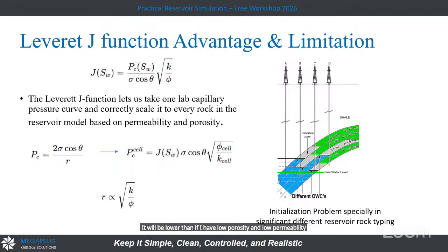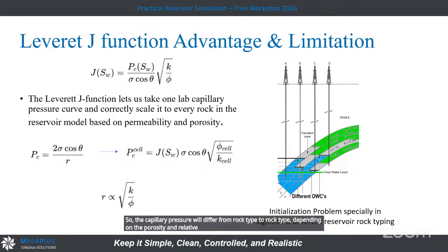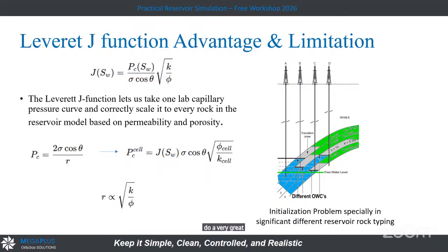If I have low porosity, the pores are very tight and the fluid is attached to the grains. So the capillary pressure will differ from rock type to rock type depending on the porosity and permeability. That's why Leverett did a very great job, and it was significant. All simulators depend on this equation, where he converted the pore throat, or this interaction, and translated it to permeability and porosity.